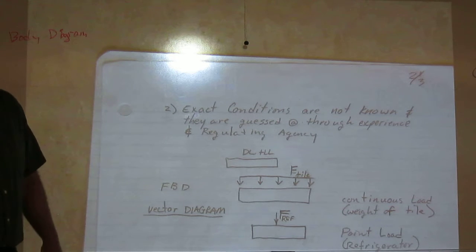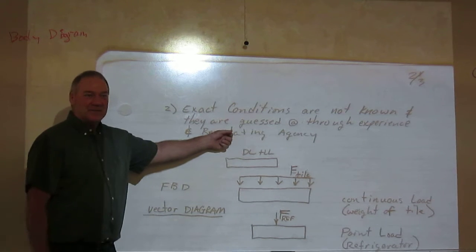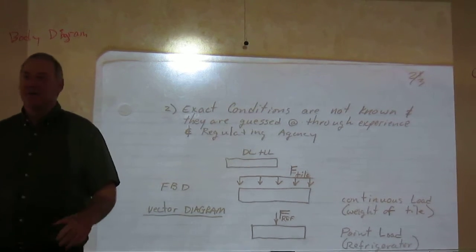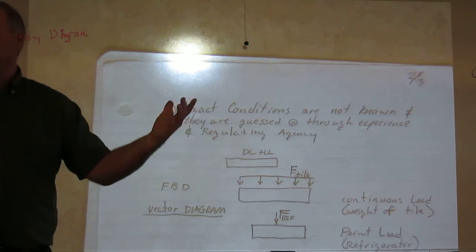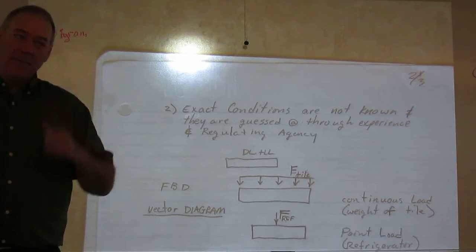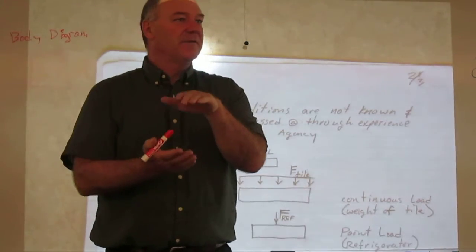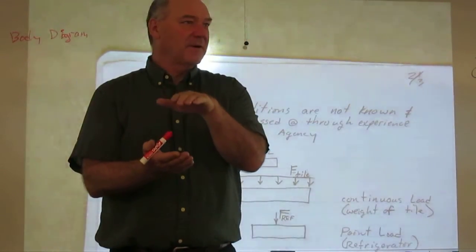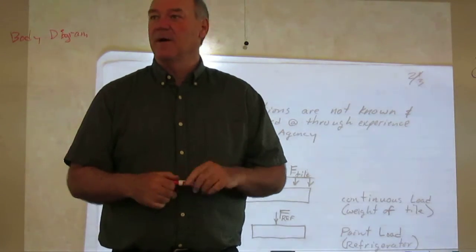No, it is. We have built enough buildings that regulating agencies have put out and said 99% of all structures will never exceed this weight. And we've measured 50 of them, and statistically that's the case it's going to be. Remember when we were doing architectural and we did the floors and we figured 40 pounds of load for every square foot of floor? That's in essence exactly what we're talking about.